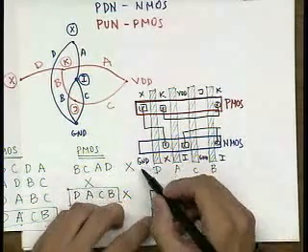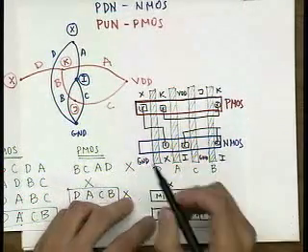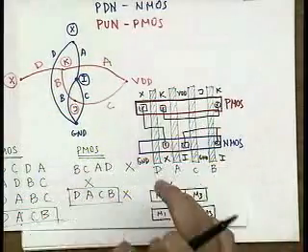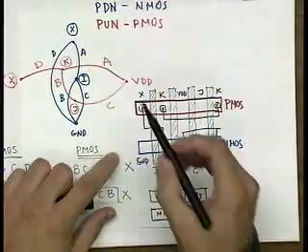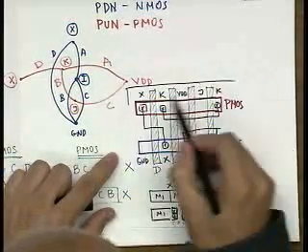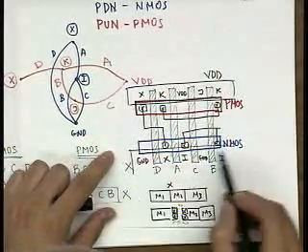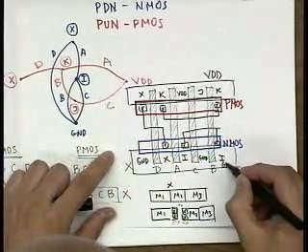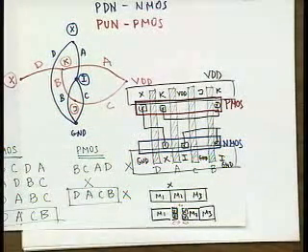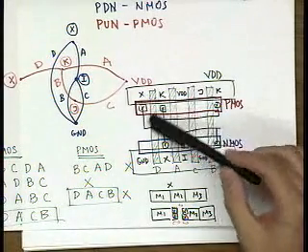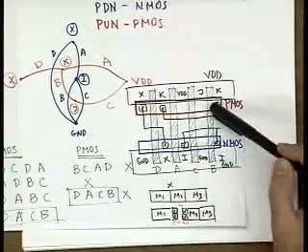And then you basically just have ground and VDD, which is already implemented over here. You remember that VDD is a stripe going over here, right? You have a huge VDD stripe over here, and then you have a ground stripe down here. So this is automatically connected, and then you finally have your standard cell layout.